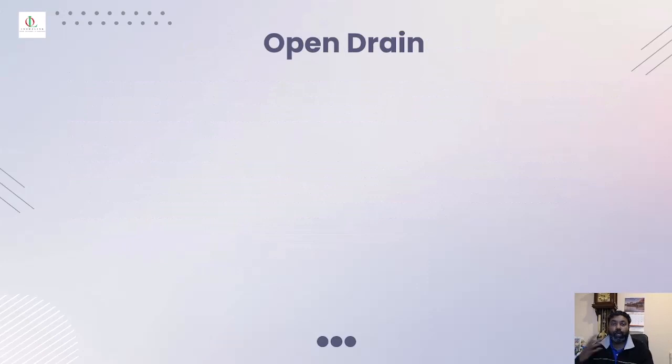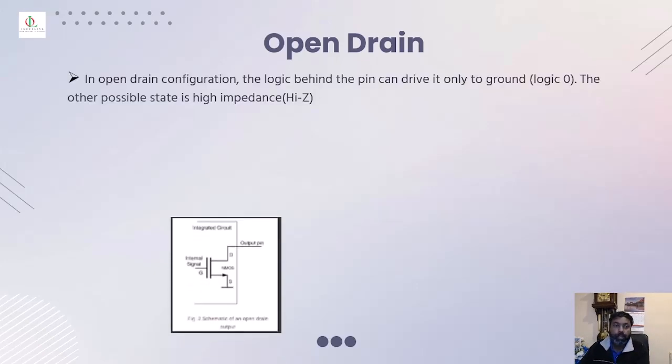So now let's move on to the second output type configuration. It's called the open drain configuration. In open drain configuration, the logic behind this pin can drive it only to either ground, logic 0, or the other possible state, which is high impedance.